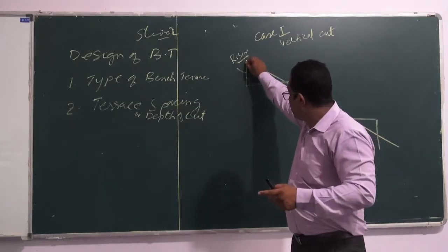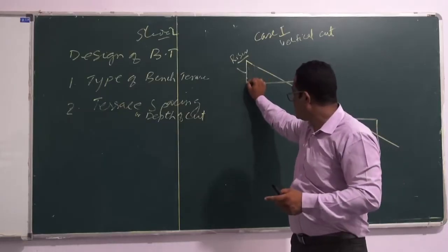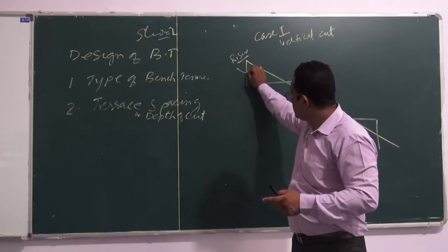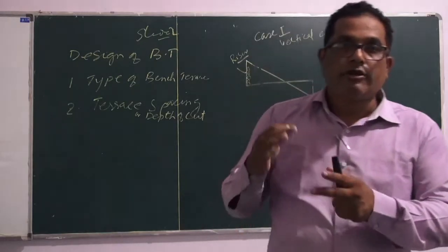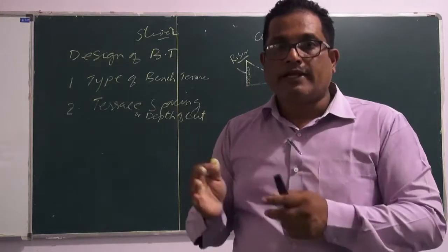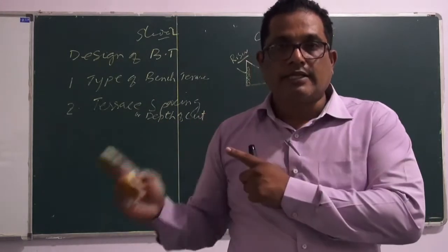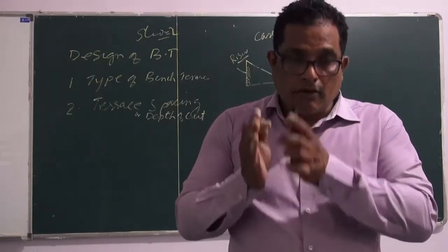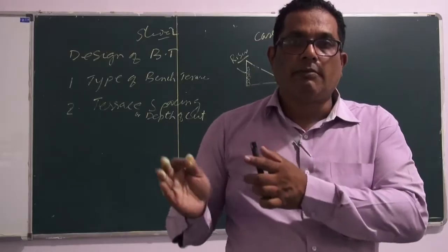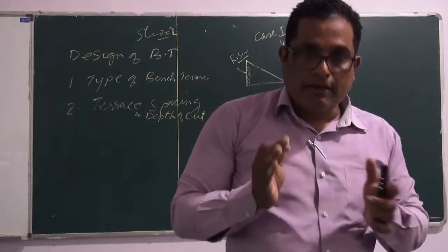Over a period of time, it will scour and it will be damaged. For such a situation, we will be required to put some retaining wall made of stones. So whenever you go for a vertical cut, first, it cannot go beyond 1 meter, and second, the thumb rule is that it has to be supported with some logs, wood, or whatever local material is available to retain that vertical type of cut.